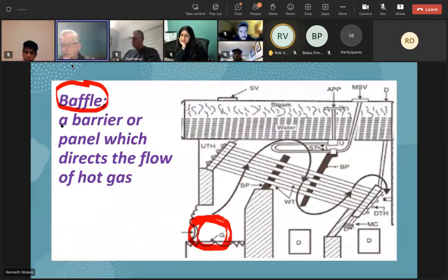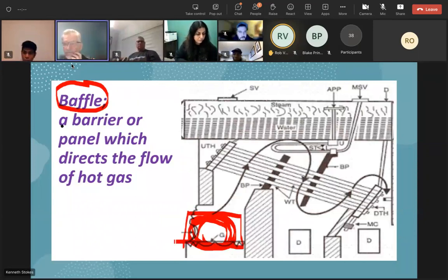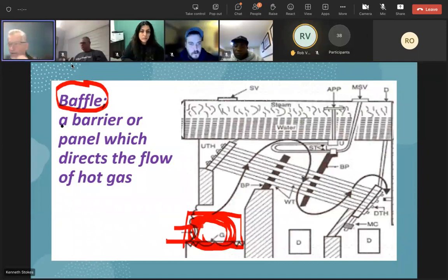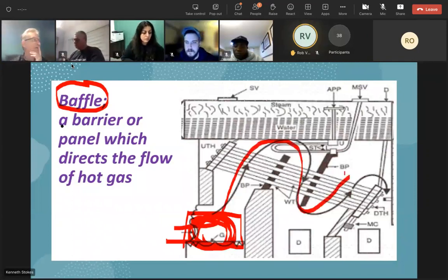It's very likely a coal burning boiler. Neat thing about older coal burning boilers, they were easily converted to natural gas fuel. Just put a burner in place of where you used to burn the coal, and you can have hot gases heating up your water to make steam.